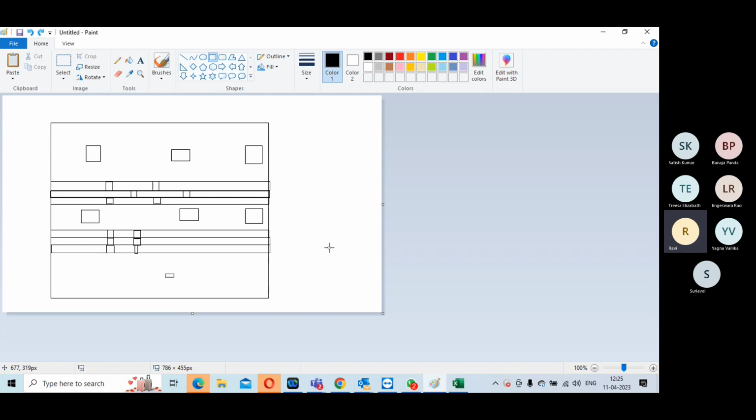Shut-off means power switches. Power gates, yes, that is called header/footer CMOS switches or power gates. What are those? Power switch. What is a power gate cell? Power gate means it will switch on the power supply to that particular block.